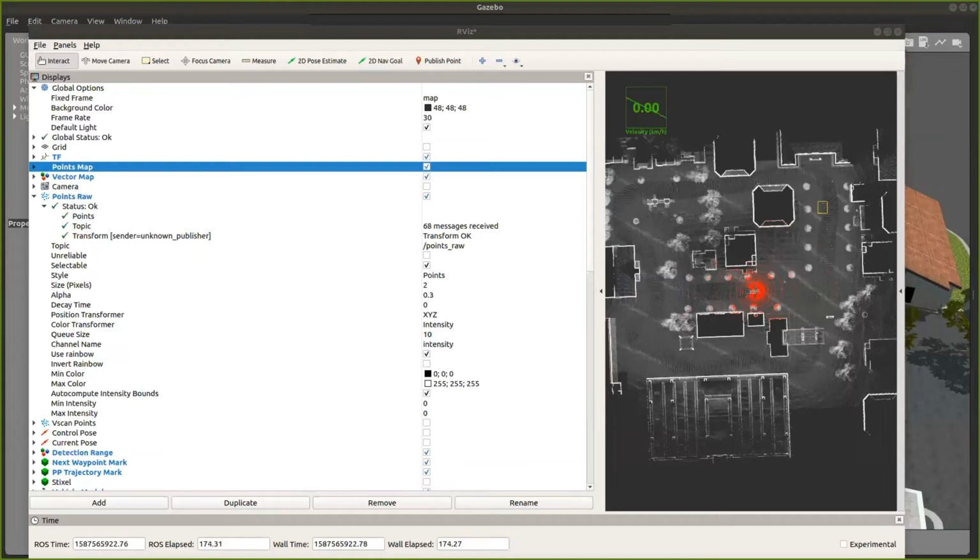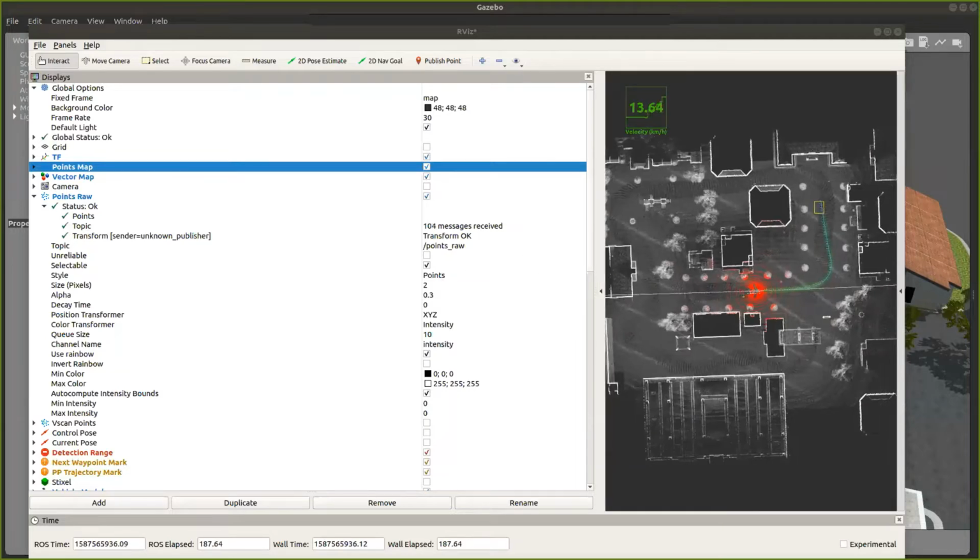Now we will ask the chassis to plan a path to the pod. The green strip is this planned path. Next, the chassis will start traversing this path. The white line is the instantaneous pure pursuit trajectory, the tracker that we're using for path following.